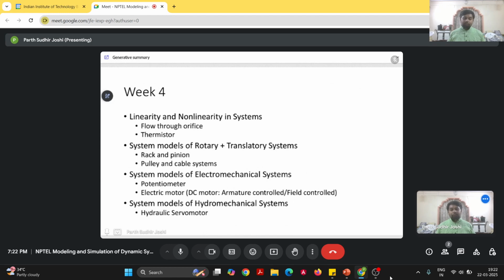We choose a particular operating point depending on our requirements. Generally in control systems, we would like to control the behavior of a system about a particular operating point, and we are interested only in small variations about that operating point. Therefore this concept of linearizing the governing equations works well for many practical applications.